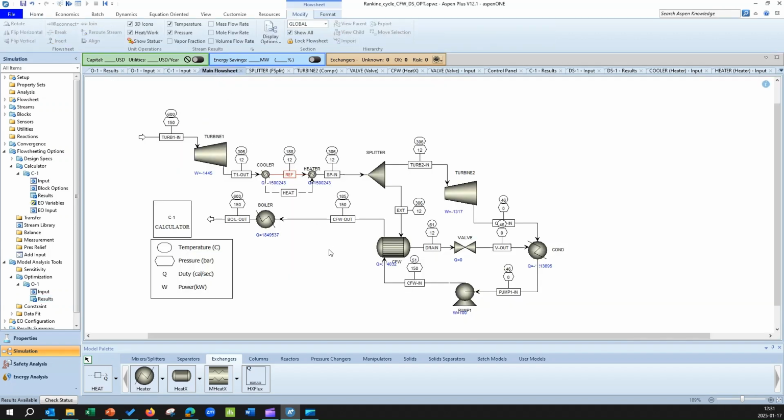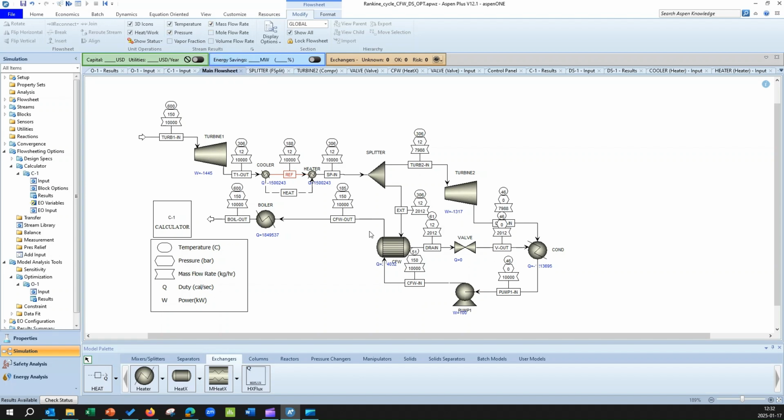We also check all this temperature, pressure, and mass flow rates just to make sure that everything looks fine. The pressure is 12 bar, so the saturation temperature is 188. We have a good TTD. DCA also works fine. If you look into the flow rates, almost 20%, 20.1% is extracted and sent to the closed Feedwater heater. So everything looks okay.